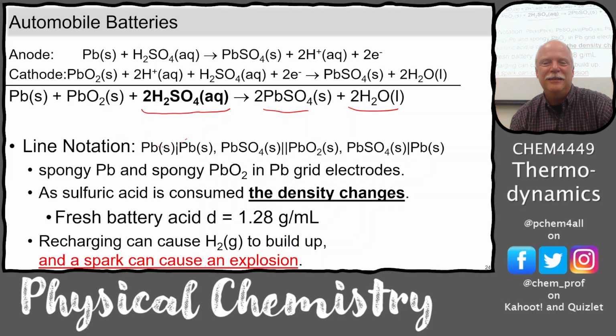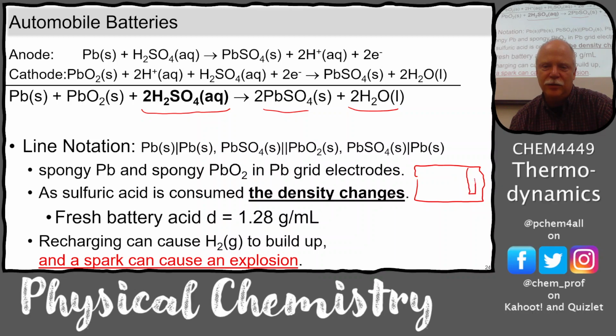Now it's neat, you can test the strength of the battery by testing how strong the sulfuric acid is. And as a kid, I remember being amazed at this. It was like an Everlast battery. It had the battery here, and inside the battery was a little tube, and inside that little tube was a fluorescent bead that was heavier or more dense than water, but not as dense as sulfuric acid. So whenever the battery was fresh, that little bead would float, and it was fluorescent yellow.